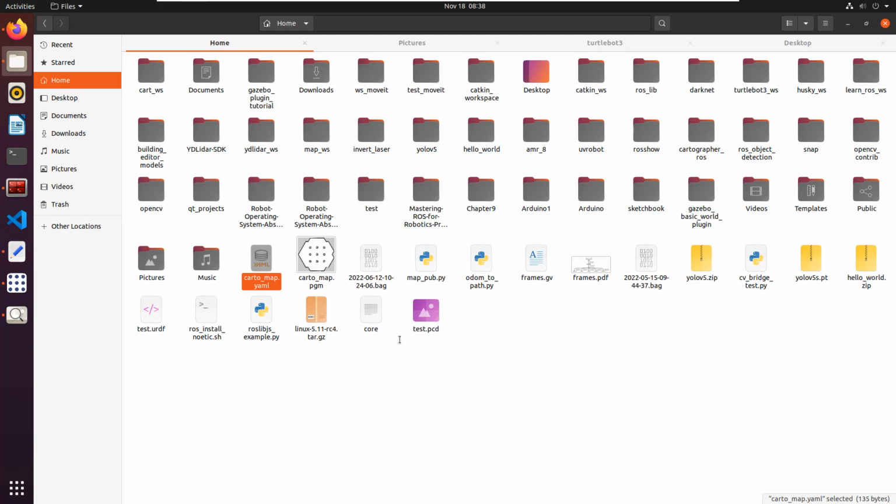One thing is that you mentioned you are running AMCL and Cartographer in parallel. I think you may be using Cartographer for getting the ODOM. Is that correct? Yes, I'm doing the whole navigation with Cartographer. Then I think you don't need to use AMCL, because Cartographer does the same thing as AMCL.